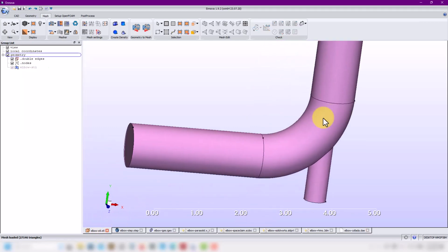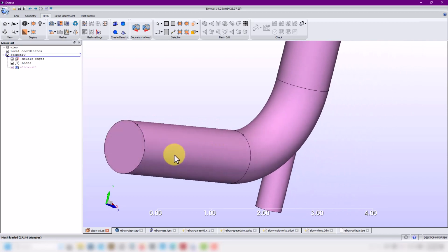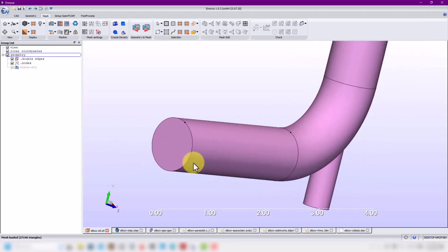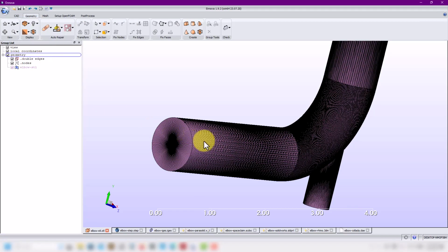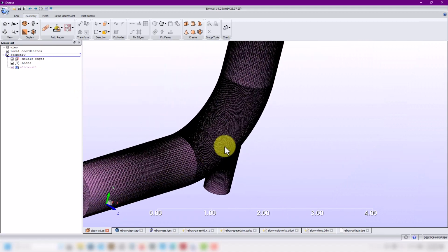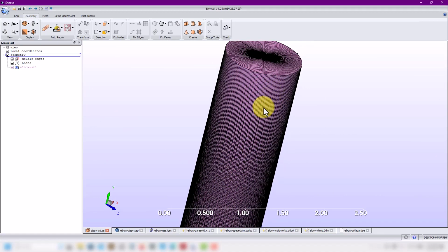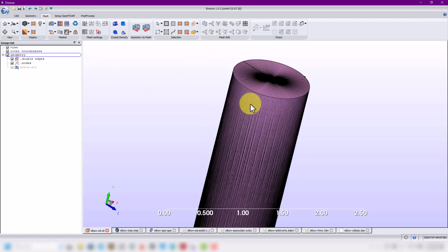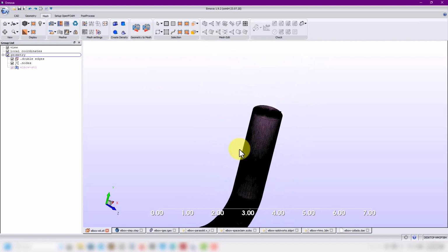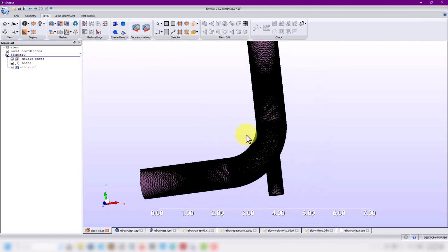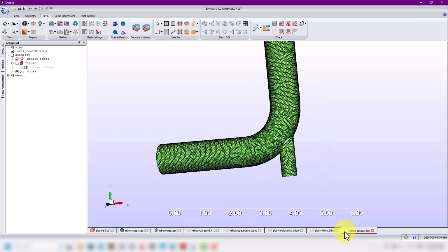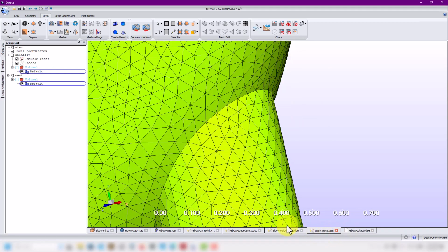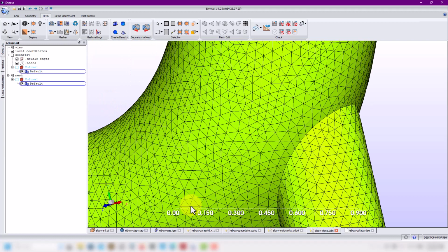So people working with OpenFOAM get used to that format because it's what is used in the meshing tools. Even CF Mesh, that is another tool, but it's not a good format. So if I go here, this is what you have, this triangulation, so it can give problems. And something cool that we have here in Ennova is that this triangulation still can be modified, so we can go here in the mesh model and we can retriangulate and so on. A little bit more advanced and something that honestly you don't need, but just to let you know that you have that option. So that being said, I just wanted to introduce all the CAD formats, and why it's important.